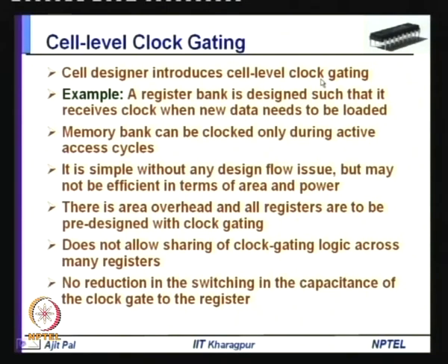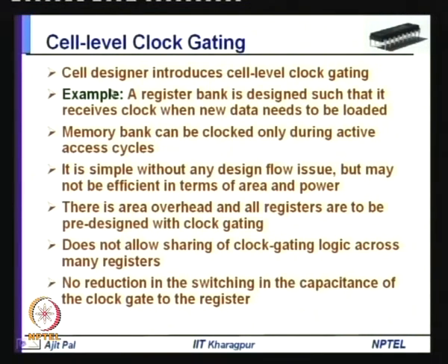So, earlier either the designer is explicitly incorporating clock gating hardware while doing RTL coding, or automatically clock gating circuits are introduced. So, it has some impact on the flow of the design. That means, you have to perform RTL level design, gate level design, placement and routing. So, it has impact on the flow, but whenever you are doing cell level design, then the design is performed